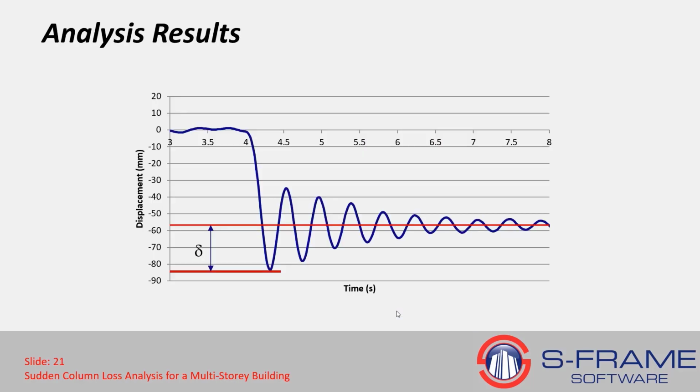If we look back into our deflection response once again, we can see there's a large influence from dynamics. If we look where the deflection is converging, around 55 millimeters, it gives us an understanding of the final equilibrium point due to the inertia of the floor. That is going down and then back up, and all due to dynamics.